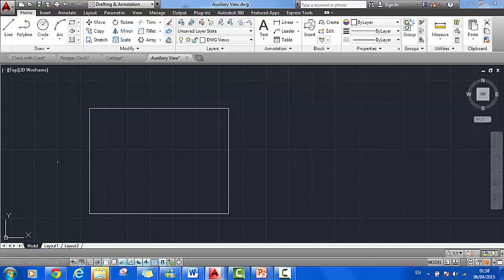Now I want to start off by drawing the plan of the object here. So now I'm going to offset a couple of these lines. I already have that offset 10. But offset the bottom line here by 10. This is giving me the starting point, 45 in from the left hand side.